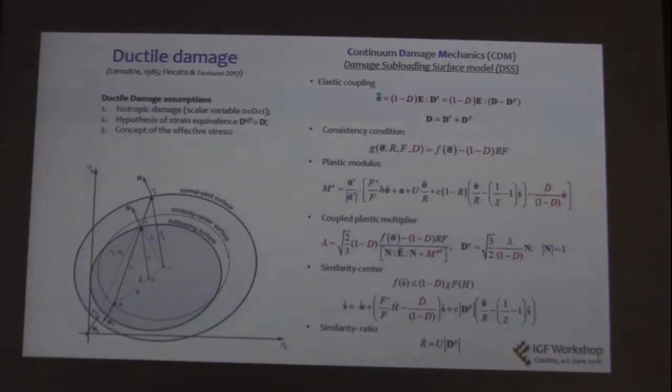The characteristic of this model is to abolish the distinction between an elastic and a plastic domain, and it allows the generation of plastic strain even in the subyield state, which is the state inside the so-called conventional plastic potential, which here is named normal yield surface. In order to do that, there is a second surface, the subloading surface, which is a kind of loading surface which expands and contracts in the stress space depending on the loading or unloading on the model.